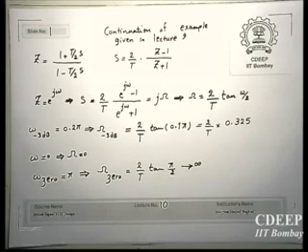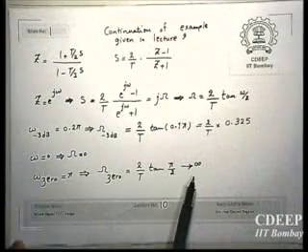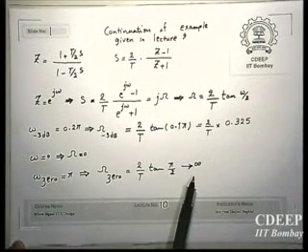Because essentially you have the entire frequency band as a characteristic, which is used for determining the characteristic of the filter. After all, by this you are compressing the entire band into a band from 0 to pi. So that is the reason 0 to infinity is mapped or warped into a frequency band from 0 to pi. And therefore effectively this 0 now will be mapped to infinity in the continuous time domain.